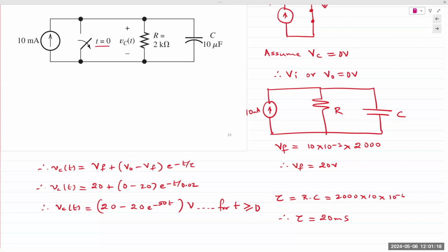How do you know that the current is the full 10 milliamps? But when the current splits up, is that the current across the capacitor? So when it begins charging, yes, it will split up. That is correct. But eventually it will reach a point where it's fully charged, and that value would equal the full current.